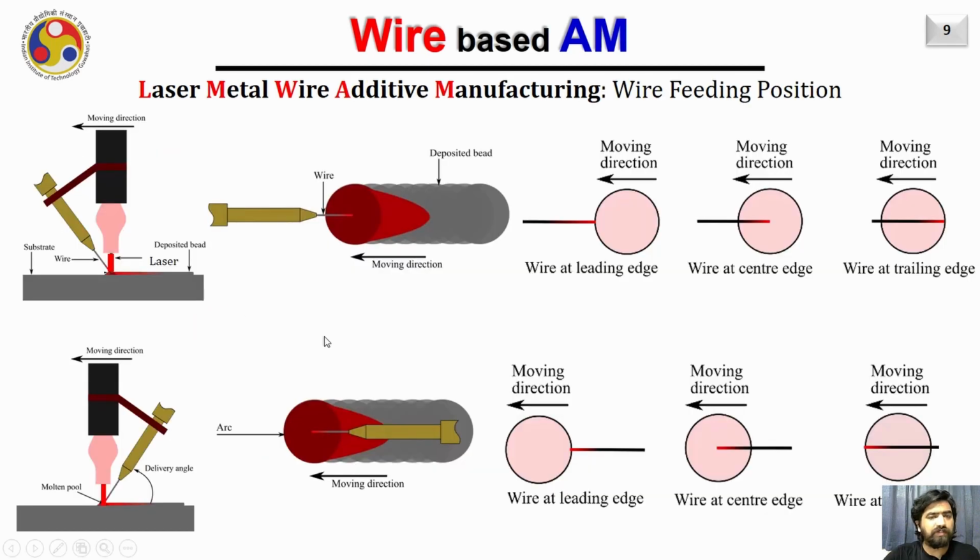This particular slide will explain the difficulties we usually face in lateral wire feeding laser cladding units. So for instance, consider the case shown here, in which the laser beam or the laser optical head is moving in this direction as shown by this arrow, and the wire is fed from the side like this.